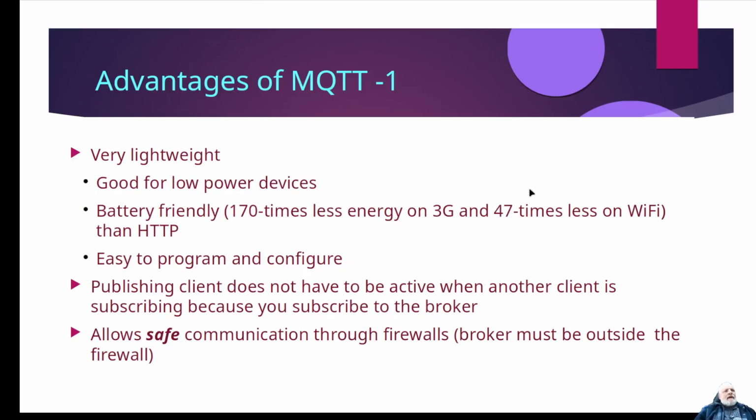All right, so some of the advantages of MQTT: it's very, very lightweight. Again, it's designed just to send a few bytes of data every so often, like temperature, pressure data, or just little bits of information about the status of machines and things based on some sensors. We're not sending videos or anything like that. And it's safe communication. It's very cool because it actually allows you to do communication across the internet, across the cloud.